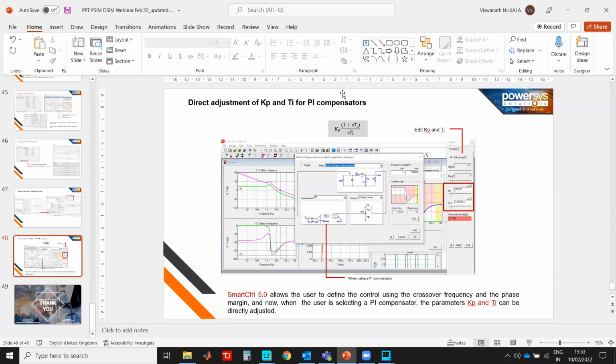Is it linked to accuracy? Yes. If the number of samples is increasing, generally you'll get more accurate results, so that you can see more points and the proper waveform. If the sampling frequency is less, the sampling points will also be low, right? So accordingly, the graph will be minimal, and you'll not get a proper waveform. At 2 times your frequency, you'll generally get good accuracy, because you are getting a good bandwidth at that particular instant.